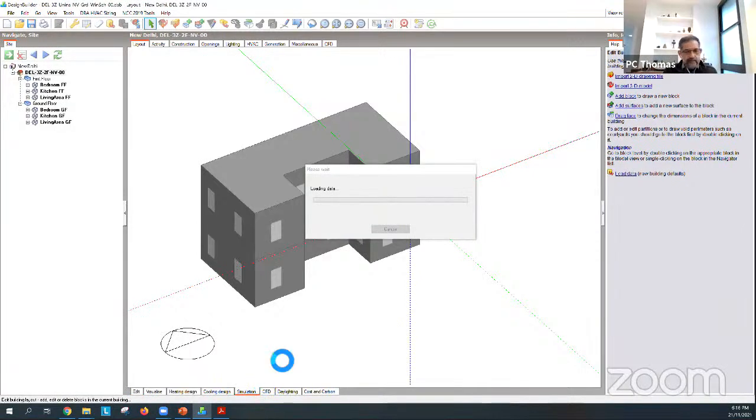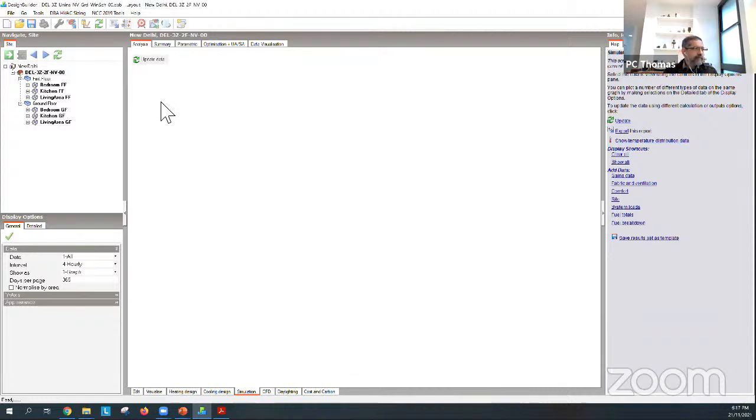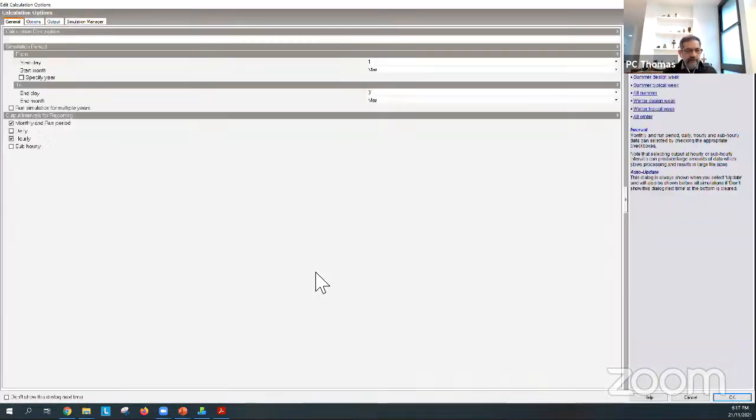It's in Delhi. So I want to test something. I don't want the whole year and then try to figure out what's going on. So I'm going to do only 1 month. And I've decided I'm going to do March. And the reason I'm going to do March is it's a swing month. It's what we call an in-between month. It's not really that hot. It's not that cold. If natural ventilation was possible, then March is a good month to try and test what's going on.